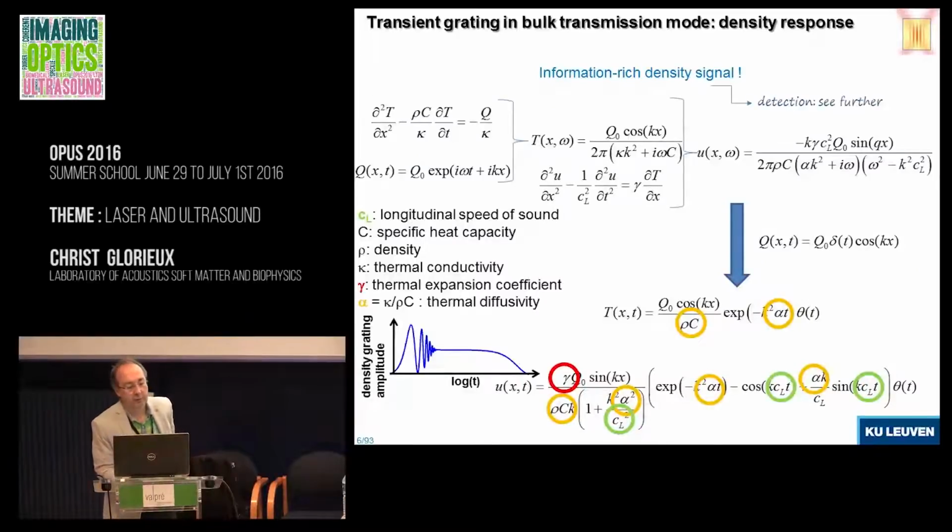So the two equations that we need are the Fourier equation that describes heat diffusion. Q here is the heat source. The relevant properties of the material are the density, the heat capacity, and the thermal conductivity. The heat source, as I said, to make it simple, and because it's also useful in practice, we use sinusoidal in time and in space initially.